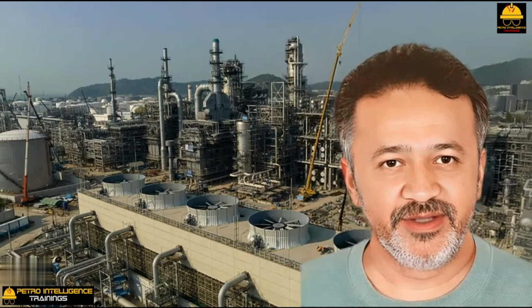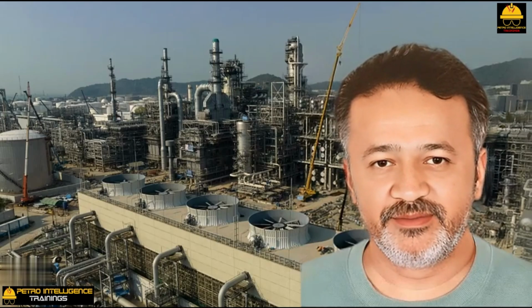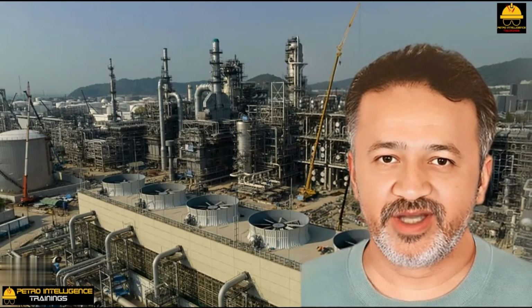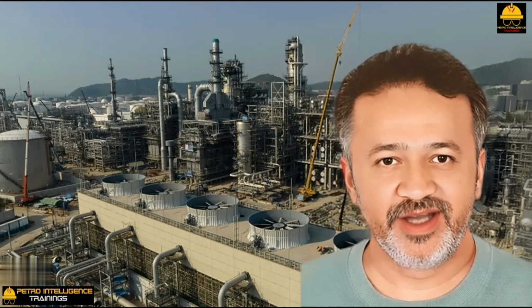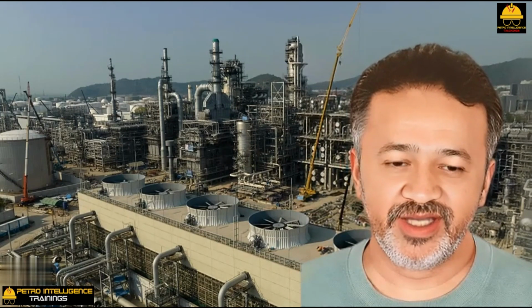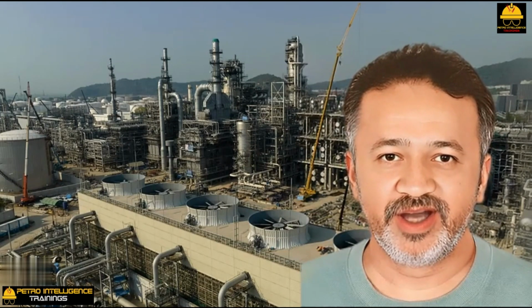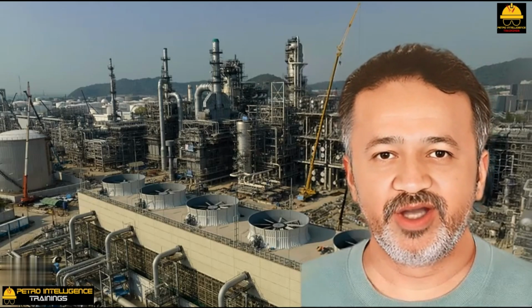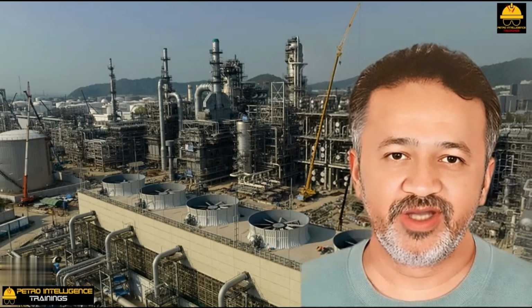All these large systems had one problem in common. They all tended to have higher flows through cooling banks connected closest to the inlet and/or outlet headers. The higher relative flows were indicated by both higher air outlet and higher process outlet temperatures. A good example of this is shown in the picture.